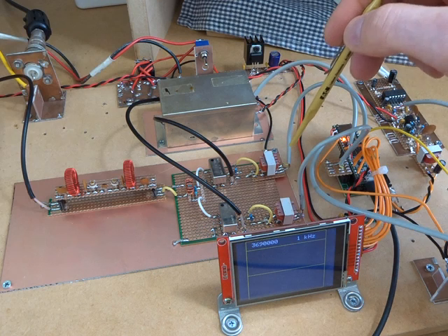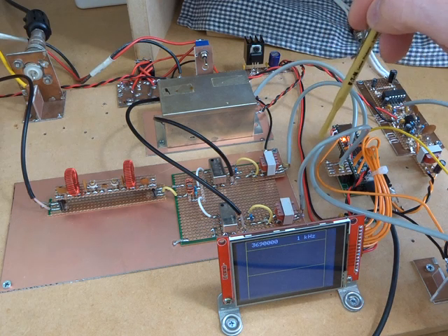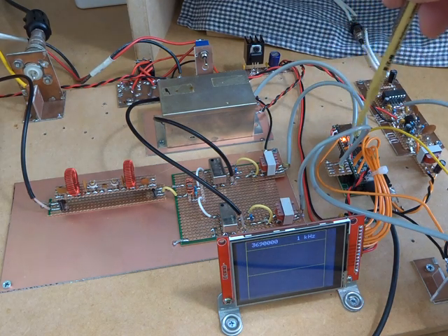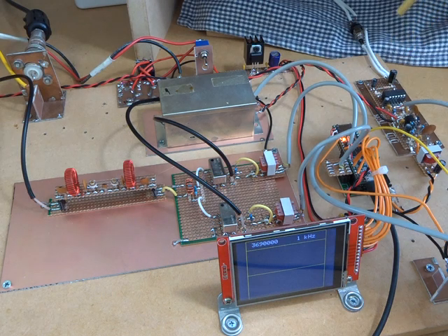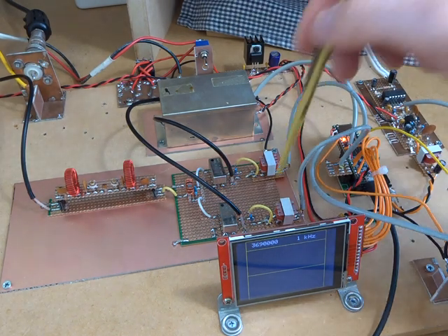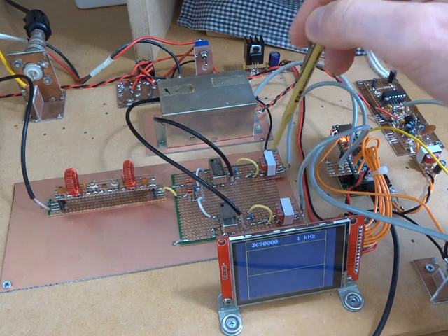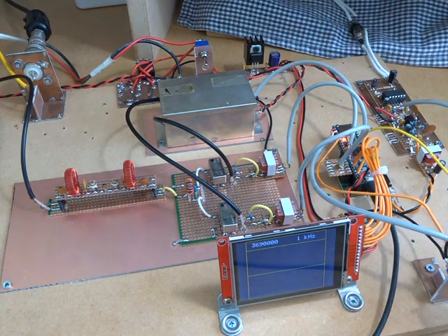I did that just to well and truly break any ground loops, and it also cut down on what I was terming DSP whine, but I think it was something else. Suffice to say, the addition of those transformers, which I must admit is standard practice with these sorts of radios, certainly helped with that. That is the only change since the last video.